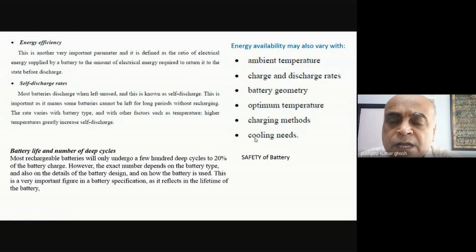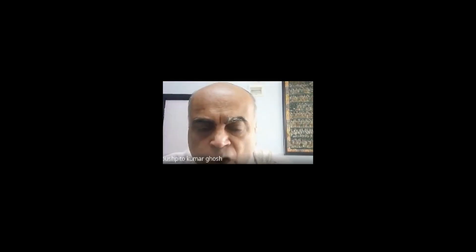For example, if instead of plugging it into a 12-volt adapter, suppose I just straight away put a 120 volt or 220 volt line. Can you imagine what will happen? There'll be a surge of current, and because of that, there'll be a heating up of the battery, because every battery will have an internal resistance, and so when I've got more current flowing, the heat that is produced is I squared R, and so there will be a heating, and your battery might get completely damaged in the process. All clear?